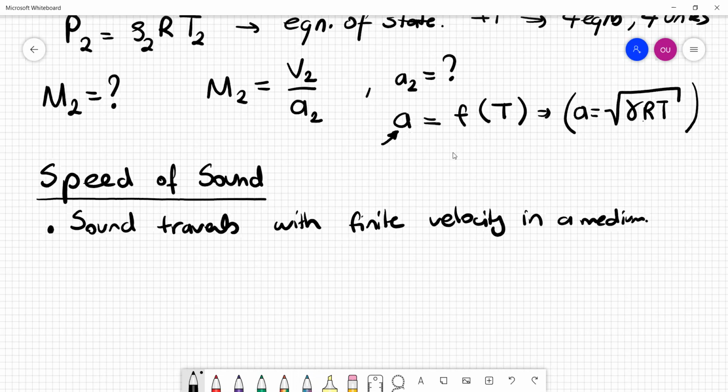We see waves of small pressure disturbances propagating out. If you have a small point where you have created a pressure disturbance, it will create waves that propagate out, and their propagation speed will be the speed of sound, A. These waves are like the waves on the surface of water when you drop a small piece of rock.